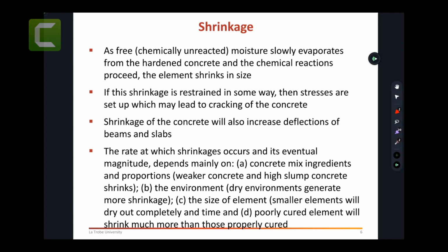Whether it's for a swimming pool, for example, depends then on what crack control we need to achieve. Is it low? Is it moderate? Is it high? Then based on that, you're going to choose the correct formula and just double check that the steel quantity you had for strength is already doing this job for us. If you need more steel, then just increase the steel more. Okay, you don't add them to each other. So the crack control steel is not added to the strength steel. No, you just go to the worst case scenario. Okay, because the line of stresses are different. So that was point B.